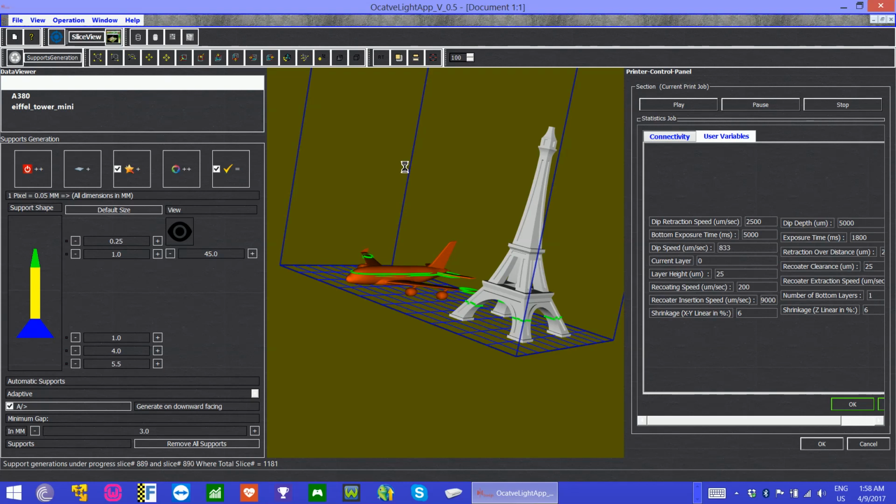So materials are the most challenging thing in 3D printing. Right materials and curing of the materials is very important. Plastic materials are basically cured by ultraviolet rays, UV lights. 5000 milliseconds is required to cure a layer by UV light.